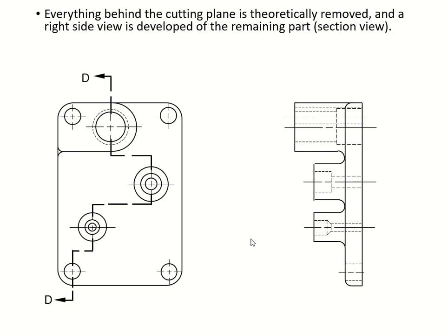Okay, so here is our cutting plane. Since you have internal features scattered all over the object, we have to cut it, bang, change the direction, go, change the direction, and then out. You've got to include all of the internal features. This is symmetric, so we don't have to. If you cut it here, you will be missing this. If you cut it here also, you will be missing all of that. So make sure you include all of it in offset sectioning. I hit everything here, and make sure you change your direction according to where your internal features are.